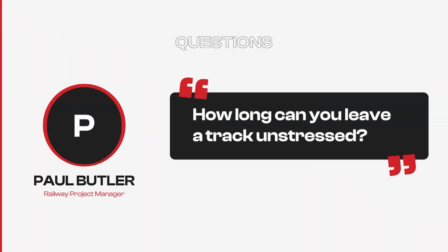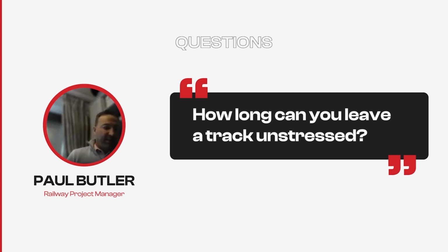So the first question is, how long can you leave the track unstressed? If your track is unstressed, you have to make an assessment, and that's certainly in the UK clearly prescribed. That will be based on your radius and the condition of the track, but more importantly on what the stress-free temperature is at that time. So if you have a disturbance or you release the stress in the track, you need to take the temperature at that point, and that will allow you then to risk assess.